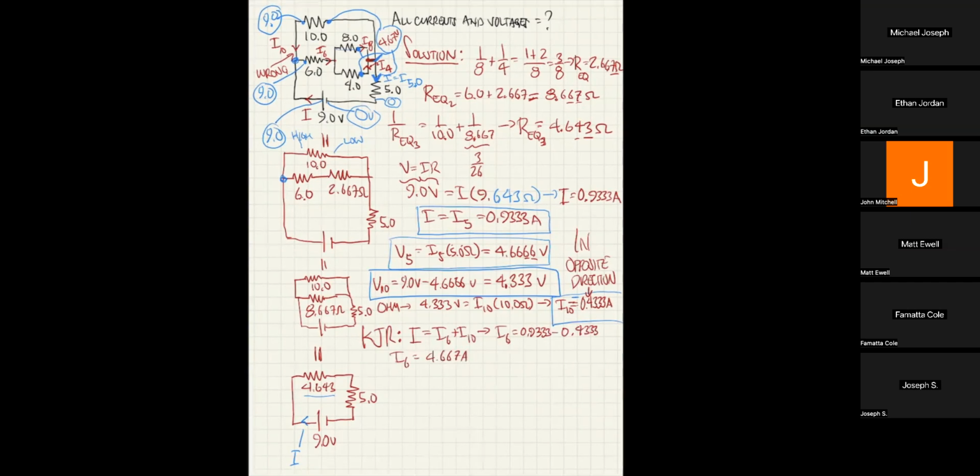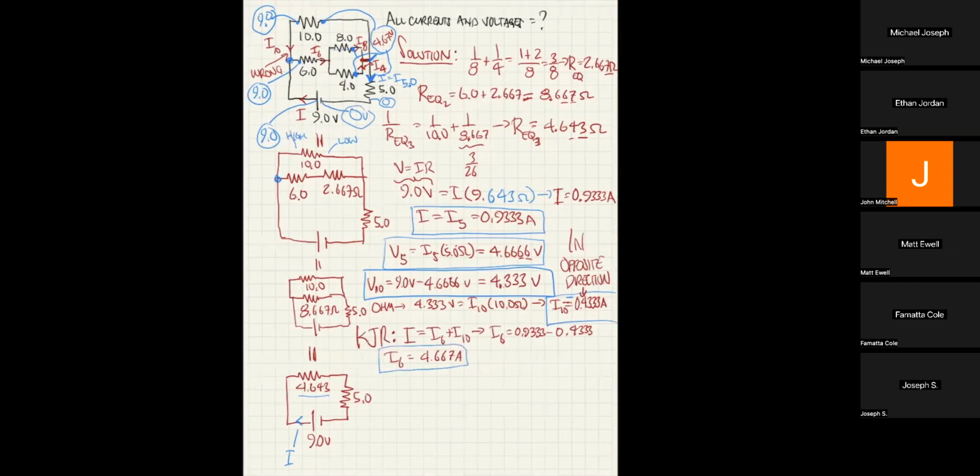So I've now got another answer for I6. And in fact, that allows me now to determine what the voltage is at the right edge of 6. We know that V6... Yeah, that should have been 0.433. Let me make sure I even did the right... Oh, that's what happened. Thanks for catching me on that. I copied that identical number, but it was the voltage, not the resistance.